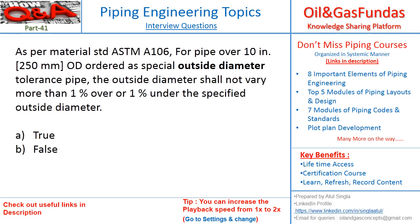As per material standard ASTM A106, for pipe over 10 inch OD, ordered as special outside diameter tolerance pipe, the outside diameter shall not vary more than 1% over and 1% under the specified outside diameter. Is it a true statement or false? So the correct answer is A. This is a true statement.